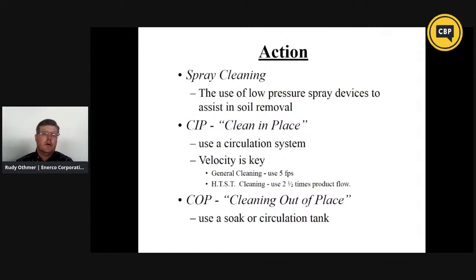And then mostly in the brewery, the parts that we're most interested in, at least, is CIP, clean in place, where we generate a small volume of cleaning solution and pump it around, spray it inside of our vessels, and it pumps through our hoses and so on and so forth. And then there's COP also, cleaning out of place. We use that in the brewery, as you know, for fittings and hoses and screens, that sort of thing.